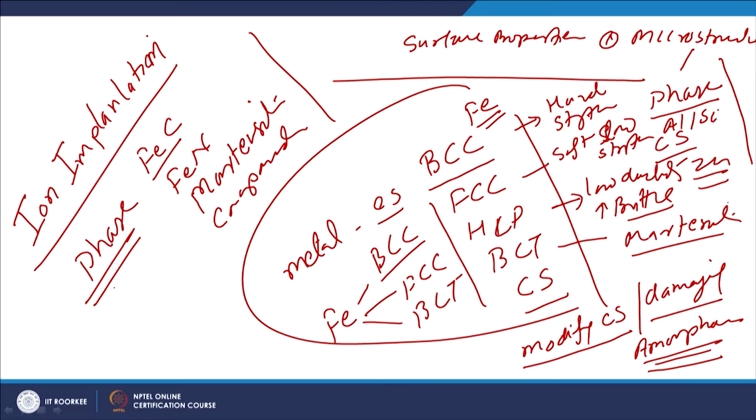In this technique, the other thing achieved is the formation of typical compounds and phases, with the help of ions of suitable elements, which improve the properties. If nitrogen ions are used, nitrogen is introduced at the surface of the metal and reacts with the metal to form the corresponding nitride.